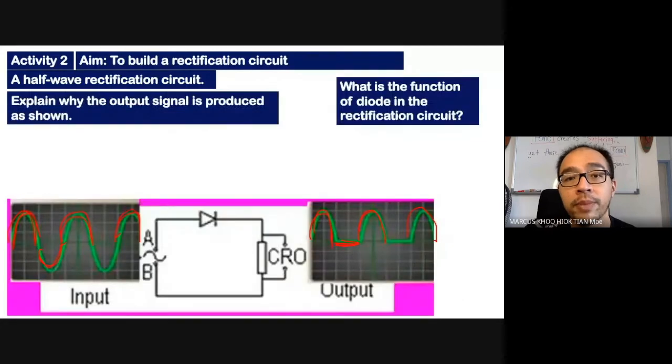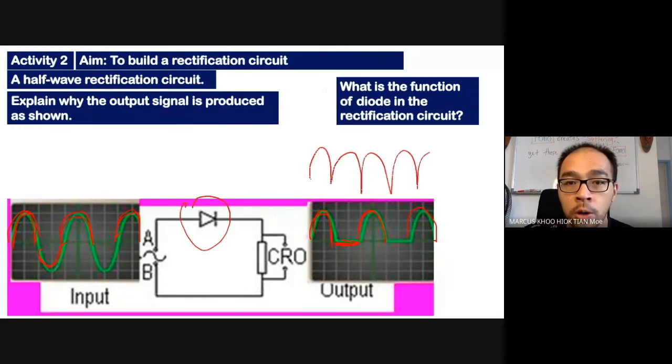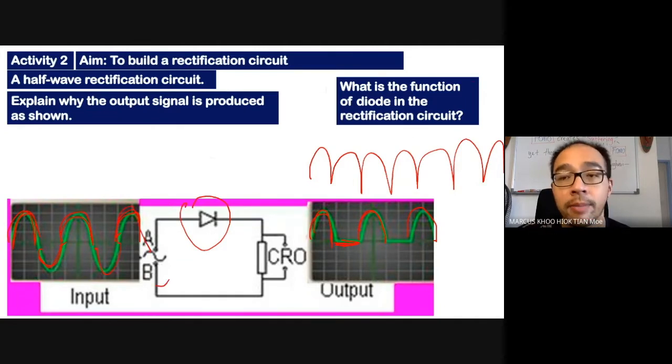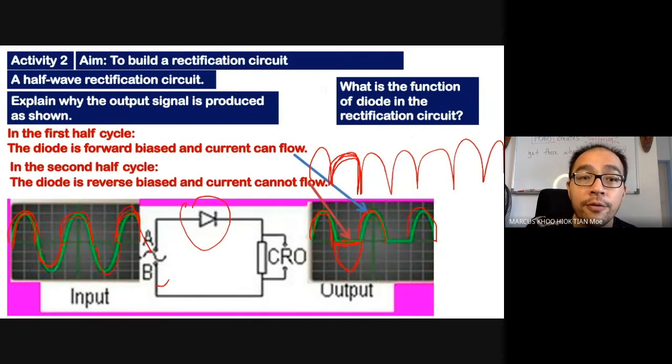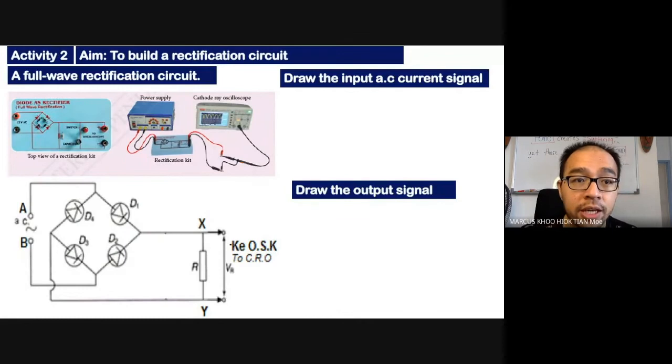Okay, so because of that, we need to do something over this circuit so that it is always on, but direct current. The problem is this is on, but it is alternating current. I do not want that. I want direct current to flow. So I need to make sure that this bottom half becomes like this. And that's why we have the full wave rectification circuit.